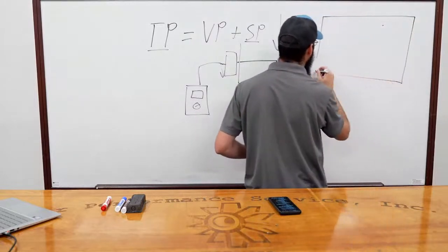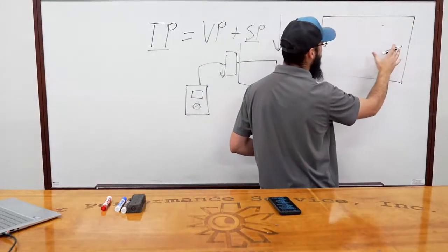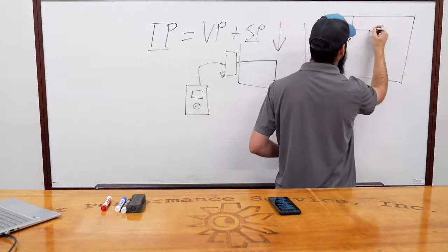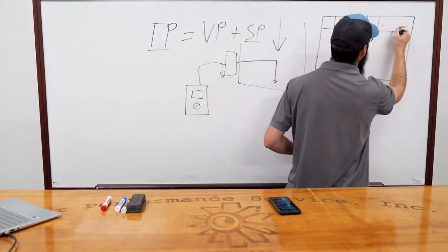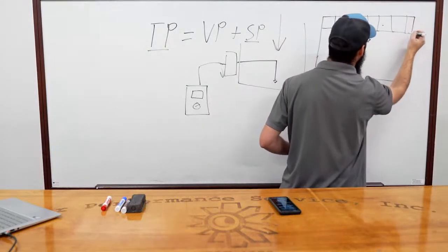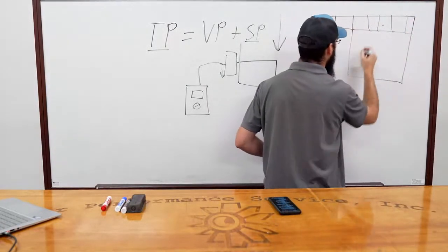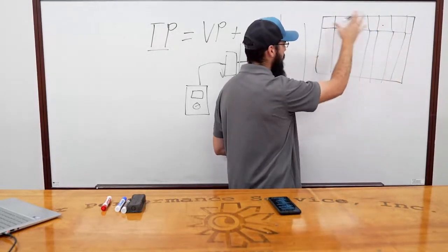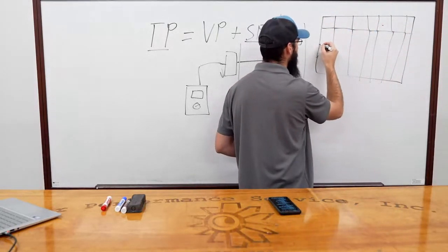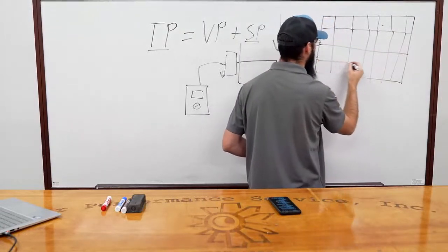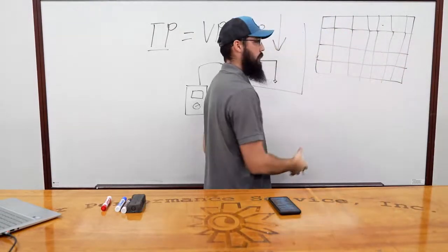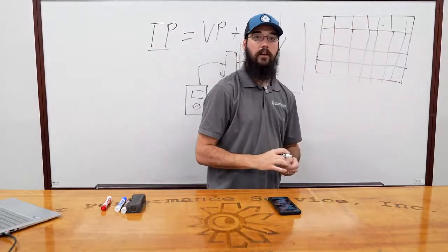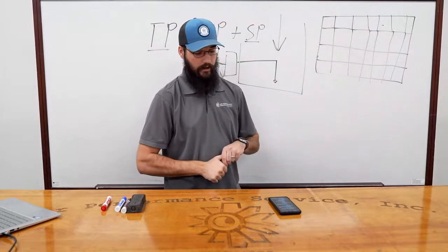whether this would be the return duct or at the face of the coil, you would essentially create little zones. Let's say this was a return duct. You would create little zones, and you would need to take multiple measurements across that duct, depending on how big it is. Now, what I'm drawing would be a larger one. In some cases, you may get away with 9 readings. In a larger case, every couple of feet, you would need to be taking an FPM.